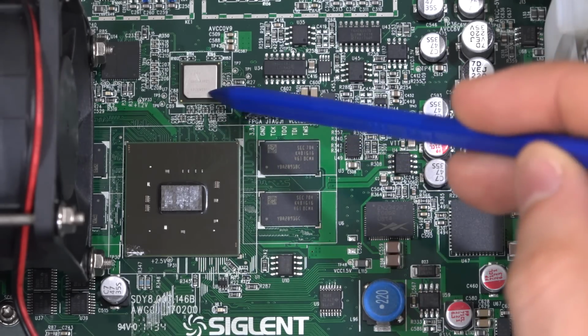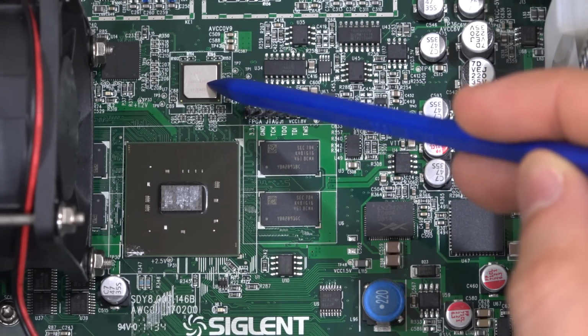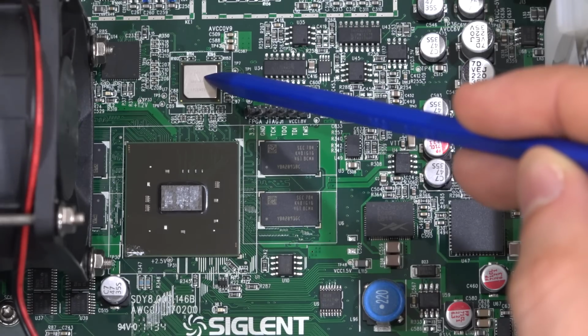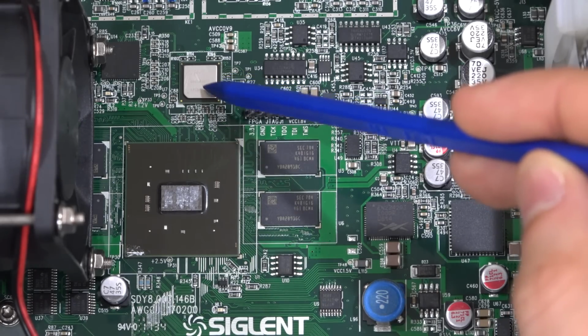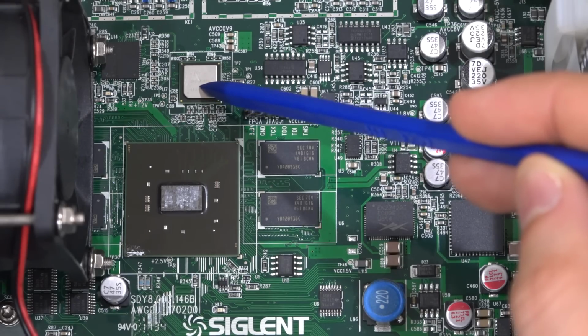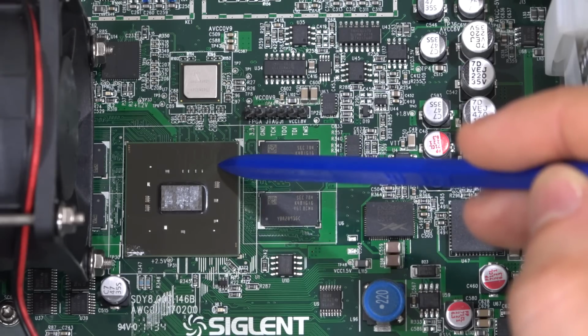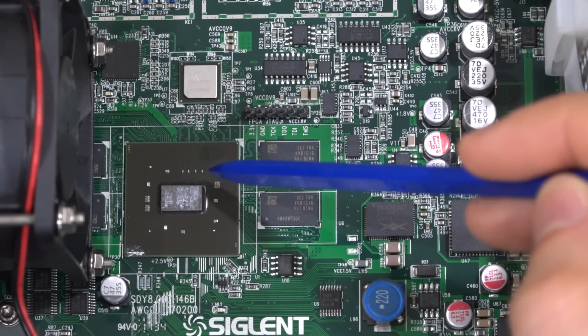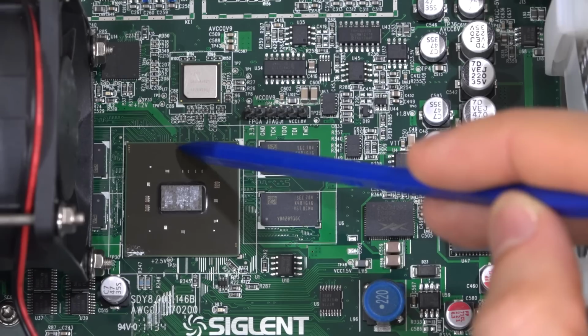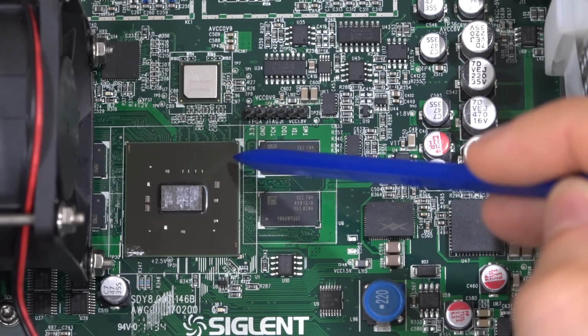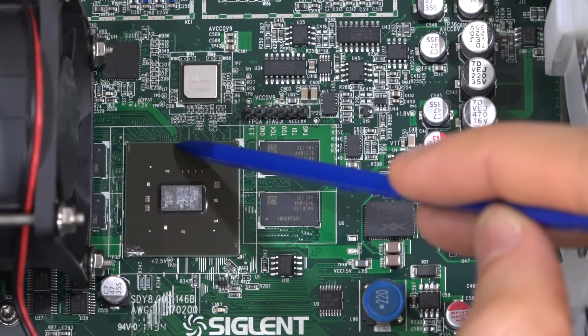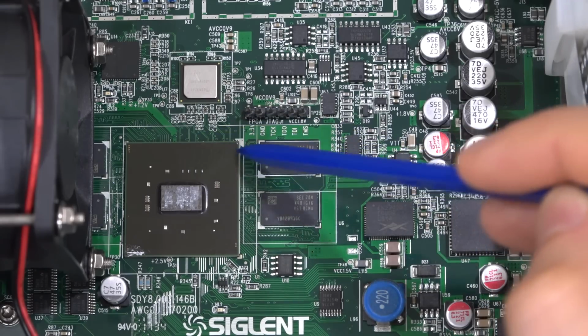Now at the top over here, we have our main DAC. Now, this is a fairly good DAC. This is a Texas Instruments DAC38J82. This is a dual channel, 16-bit, 2.5 gigasample per second DAC. Now the interface between the DAC and the FPGA is a standard JESD204B. This particular one has 8 lanes, and I think you might be able to even count them. Here's 1, 2, 3, 4, 5, 6, 7, and 8, I think. Did I miss one? Either way, there are 8 lanes going over here.